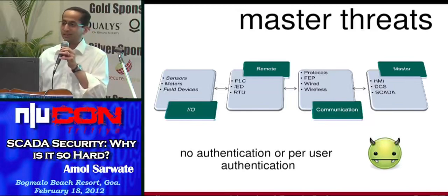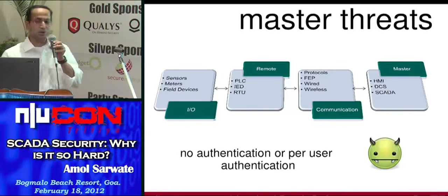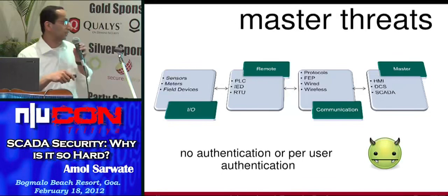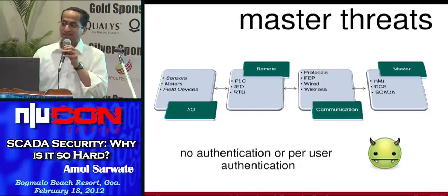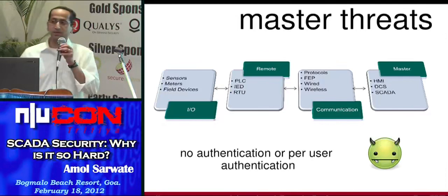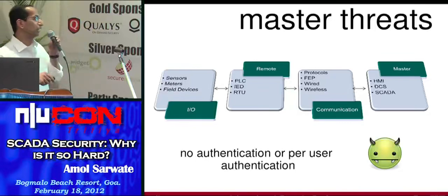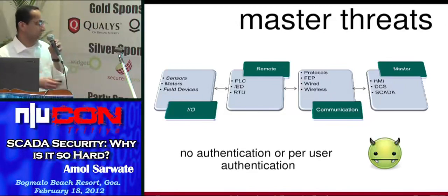And that was fine while the networks were air-gapped. But now, since these networks are connected to the internal networks, your viruses, your worms, don't have to physically enter the room through the door. If the network is inadvertently connected to your internal network, the worms, just like Stuxnet, can jump from your internal network onto these HMI machines and manipulate them directly. So they don't even have to deal with Modbus or DNP3 or try to guess the addresses for PLCs and RTUs. They already have very easy access here, which is the SCADA master. They can just manipulate things on the SCADA master.